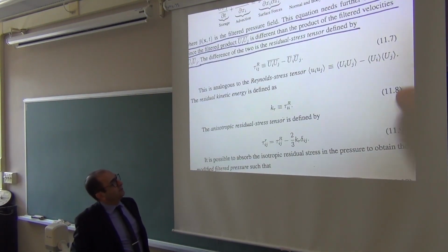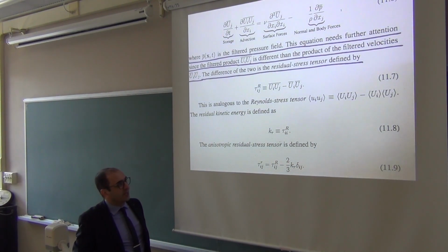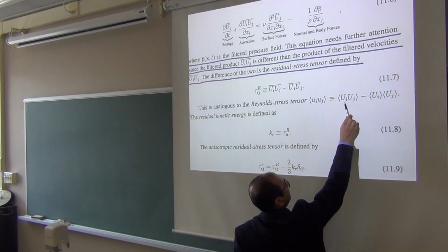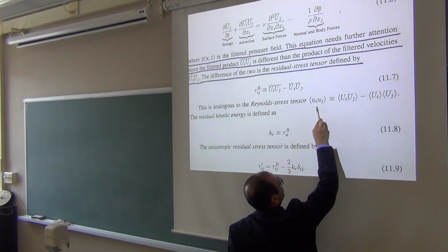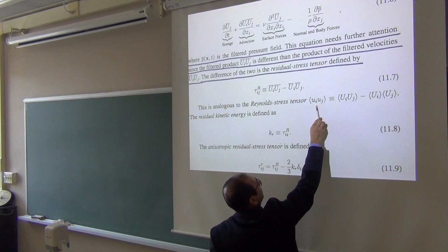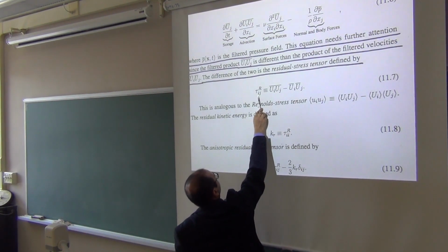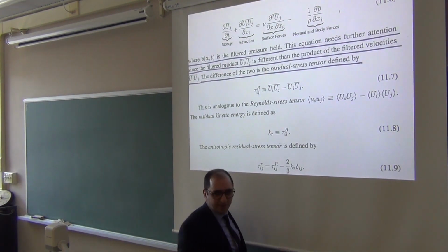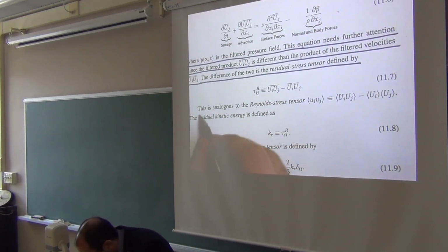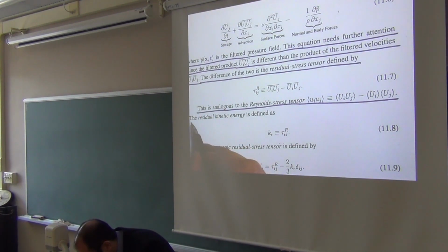And this would look very analogous to when we did it for the Reynolds averaged equations. There we had this one in the equation, remember? But we desired that one, so the Reynolds stress tensor was left, and then we parameterized it. Here, something else was left in the equation, not that one, but it looks very analogous. So it is analogous to the Reynolds stress tensor when we did it in chapter 4 or 5.